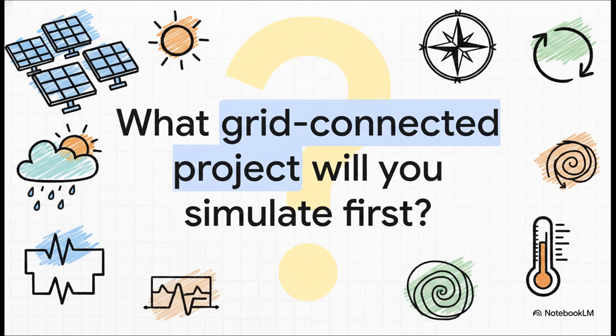And there you have it. You now have the foundation and the tools to build incredibly accurate variants. You know how to lock in the location, interpret the weather data, optimize your panel angles, string up a healthy subarray, and conquer those complex thermal losses. So it's time to grab your meteorological data, pick your panels, and fire up the workspace. What kind of grid-connected project are you going to simulate first?